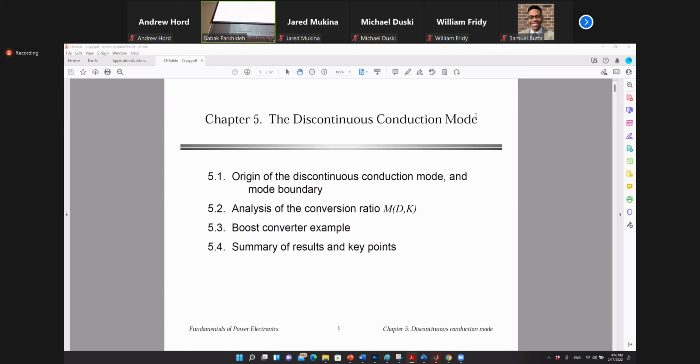So then you have a choice whether you operate this synchronously, if you know what type of device you're using, or not. Because during conduction at high current, one is order 1 and the other is a square. So if R is comparable to the voltage drop, then definitely, if you don't switch on this device, you have a better performance circuit in terms of conduction.